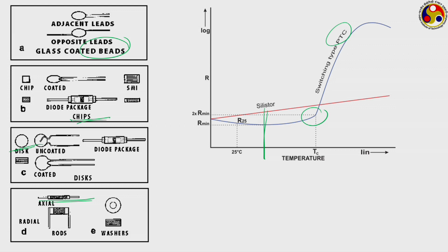These PTC based thermistors can often be used as switching devices, like a thermal switch. When the temperature is lower than this limit, the switch will remain in open position. Now suddenly, as this particular threshold is crossed, resistance will increase almost infinitely, thereby causing the circuit to stop. So this kind of thermal switch application and sometimes control switching application can be achieved with a thermistor having positive temperature coefficient. But commonly for temperature measurement or control purposes, we prefer to use materials with negative temperature coefficient.